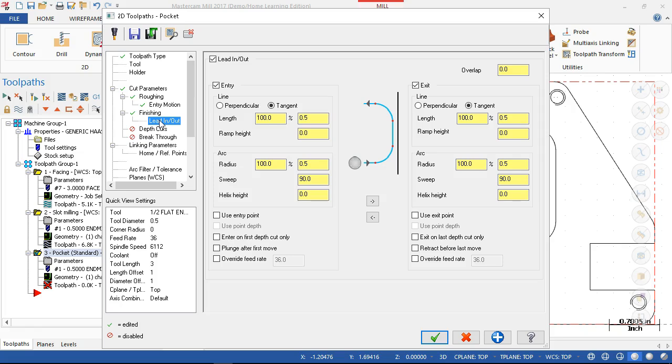When our tool is basically defined as 0, it doesn't matter. I can be as close as I want as long as I'm not plunging in material. So if this was a very narrow slot, I could go 10 thousandths, and the arc could be maybe 30 thousandths. Do I need to come in that close? Probably not, but I can buzz it that tight.